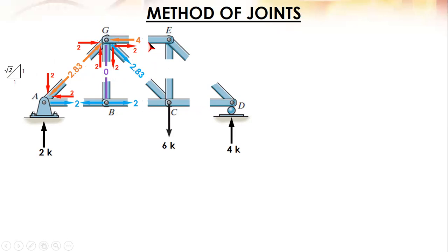And then you proceed to the next joint. Tension. Those are the components, X and Y. Okay. So you can proceed to joint E, with two unknowns, joint C, two, or joint D, two. Okay, let's go with C. Now, vertical at C, there is 6 downward. And then you only have 2 upward. So you are short by 4 upward. That is 4. And then for the horizontal, there is 2 going to the left. So balance it with 4 going to the right.